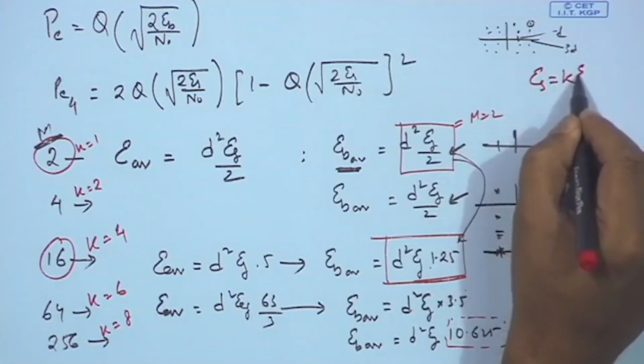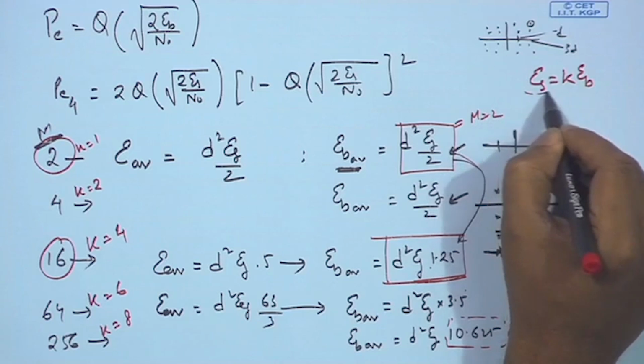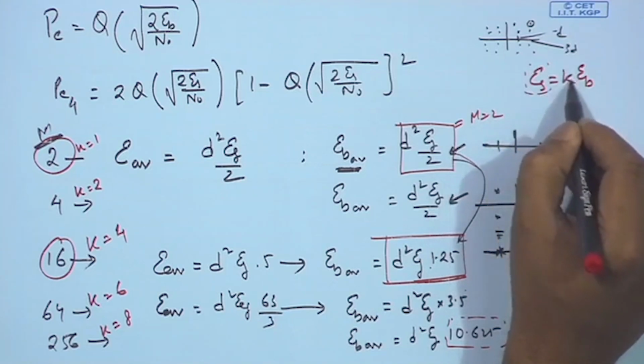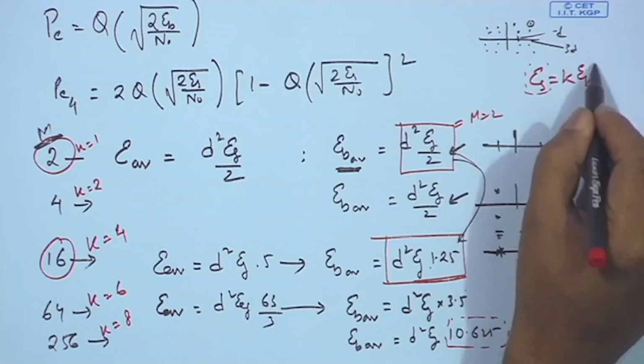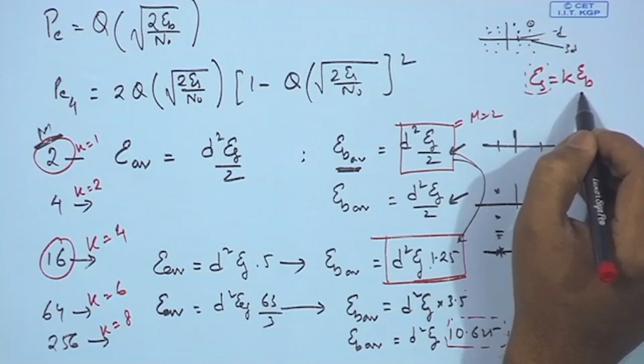Now, it is not necessary over here to repeat the similar things for M-ary orthogonal signals, because we have already shown that if you keep the energy per symbol the same and you have the relationship E_s equals k times E_b, then in case of M-ary orthogonal, if I keep the same constant E_s and keep increasing k, E_b goes down. So, in that case the energy required per bit goes down. We have been saying this thing.